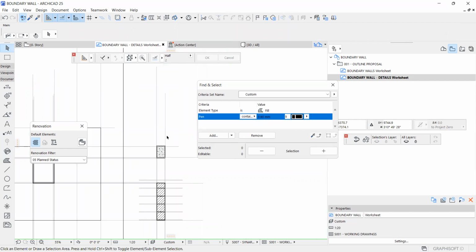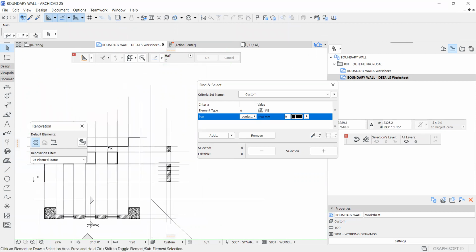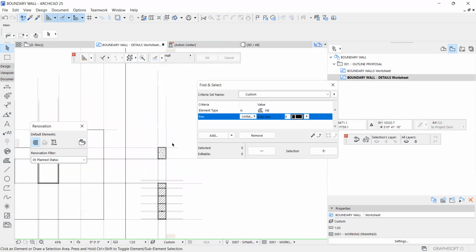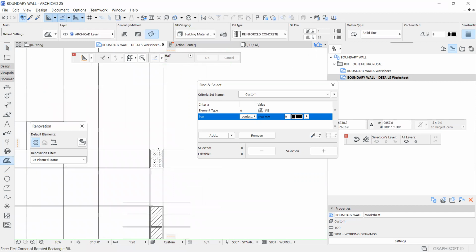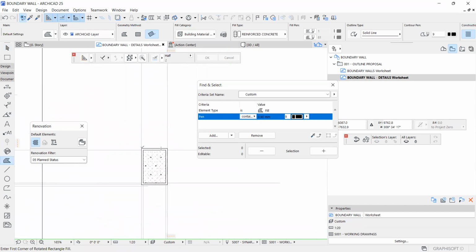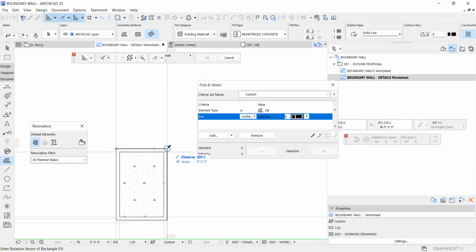Now, it takes me back to our elevation. Remember, I talked about the topping of our walls. We need to top it using a coping, okay? Now, most of the time our copings are usually the extent of the plaster, 230. Then we have overhangs of 25 on both sides. That makes it 280. And then the thickness is around 50 with the edges being 25.